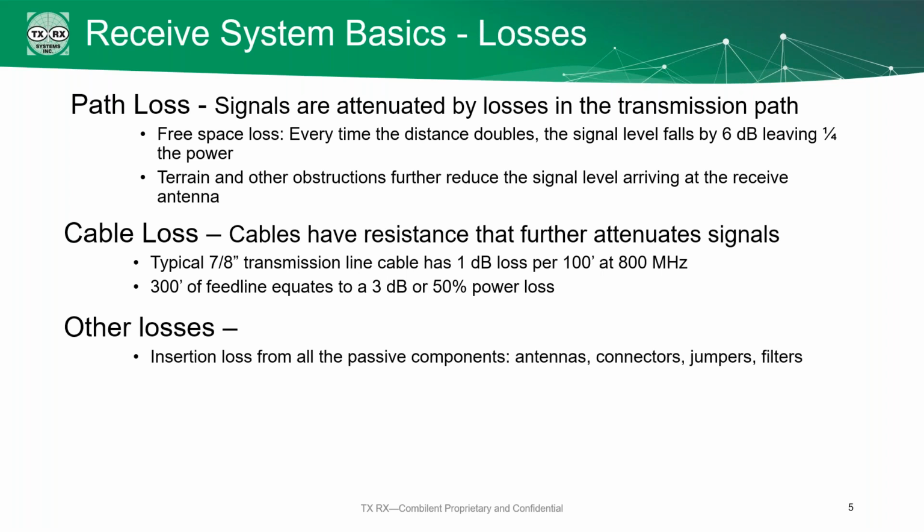In addition to those, we also have insertion losses from passive components. Your antennas, your connectors, your jumpers, your filters all have insertion loss as part of them. They're all going to degrade your signal even just a little bit. We have to overcome that loss too.